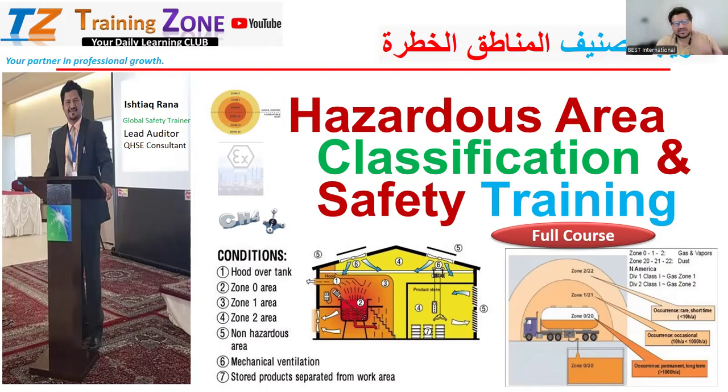What we're going to discuss is what a hazardous area is, how we classify it, and most importantly, what kind of safety measures are important, especially for hazardous areas, either zone 1, zone 2, or zone 0. On the other side, zones 20, 21, or 22 relate to combustible dust, while zones 0, 1, 2 relate to hazardous combustible explosive gases or vapors. And then, of course, we'll be discussing the combustible gases.